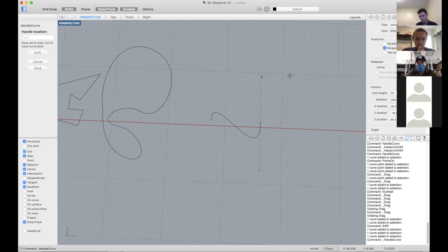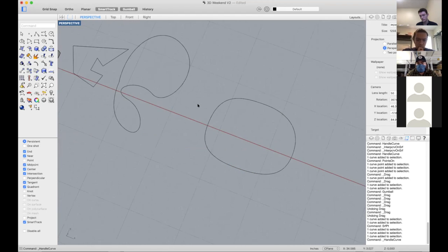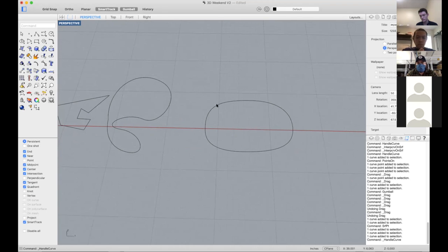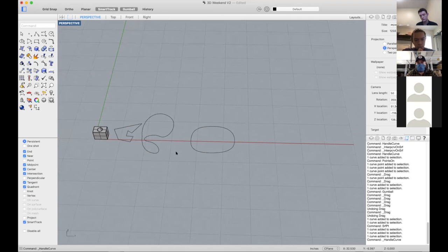You can also do that if you hold shift while you're actually moving, it'll constrain it to the same axis that you started on. I kind of didn't want to do that. So I click and then hold shift and then it'll do it. And you can come around and finish up your organic shape here. So there you go. Now it meets up nicely and it's tangent. So holding shift works for pretty much anything. It'll constrain it to one of the axes relative to whatever you just did.